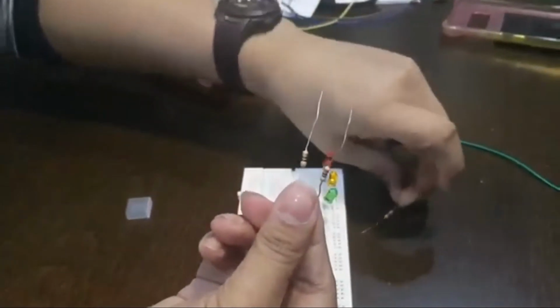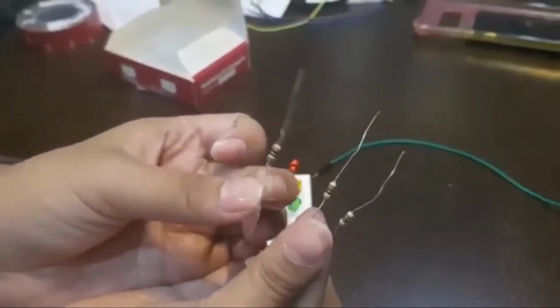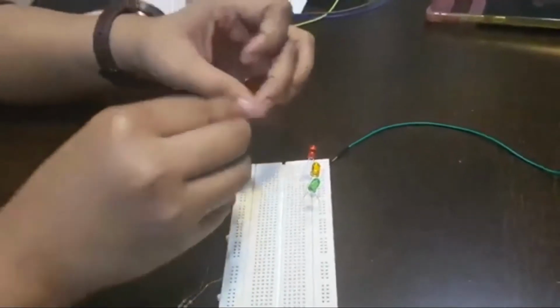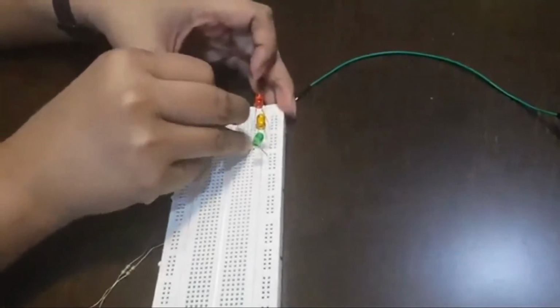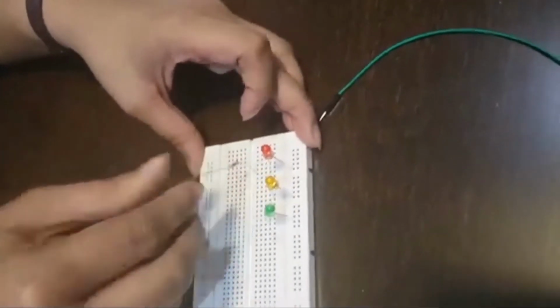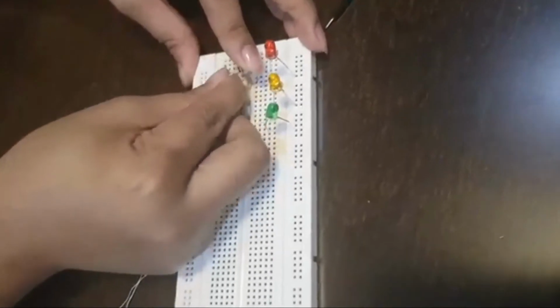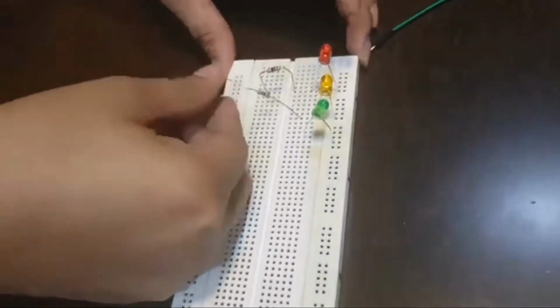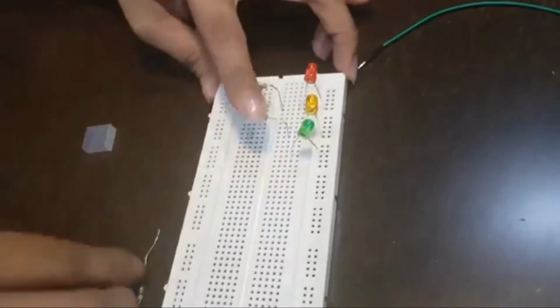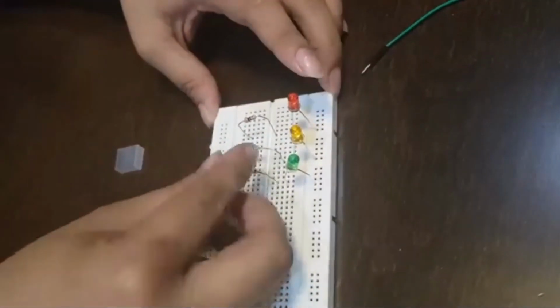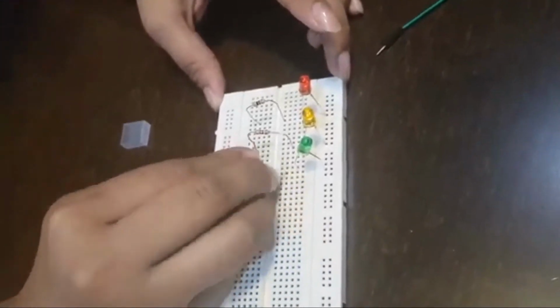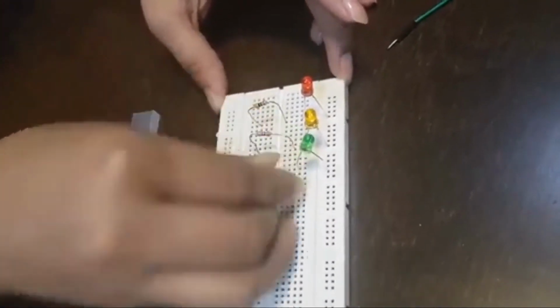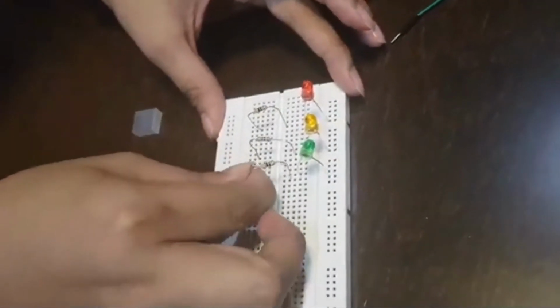We take one of the 300 ohms resistor and connect one leg in the same node of the positive leg of the LED. The other leg should take a different node anywhere in the vertically connected holes. Make sure it is not connected to any of the other elements. The resistor regulates the current flow to the LED. This way, it would not damage the LED or the Pi. Each LED is now connected to a 300 ohm resistor.